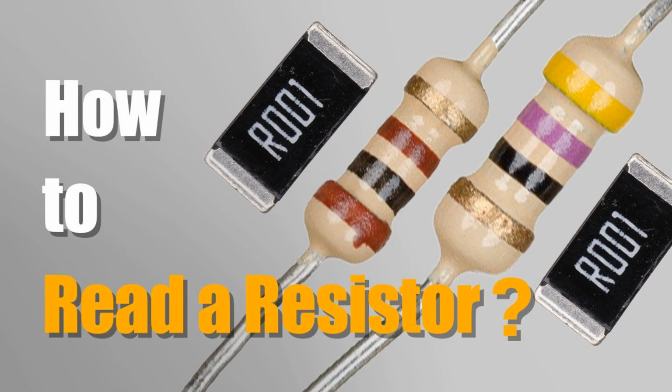Design considerations. Resistor value. The value of the pull-up or pull-down resistor should be chosen based on the current requirements of the circuit. Common values range from 1 kΩ to 100 kΩ, depending on the input characteristics and the speed of the circuit. Higher resistor value: less current consumption but slower response time. Lower resistor value: faster response but higher current draw. Internal versus external resistors. Many microcontrollers and logic devices have internal pull-up or pull-down resistors that can be enabled via software, reducing the need for external resistors.